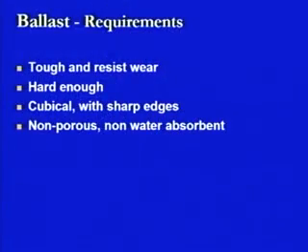Then it should be non-porous in nature and it should be non-water absorbent. If it is taking more water, it is an indication of losing strength. So, if a material takes more water, it has lesser strength. If it is taking less water, then it has more strength. So, this is another requirement of the ballast.